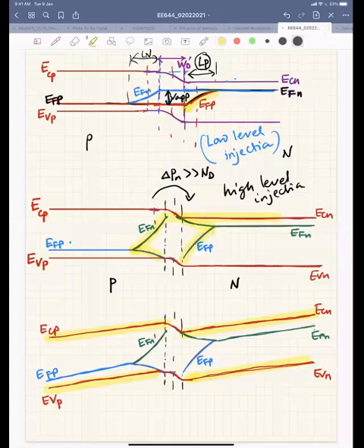See, some diodes come with a current limiting resistor, but then it could withstand a little bit more current or more applied voltage. You could connect a resistor in series with the diode. Basically, you are applying a voltage, then dropping some part of it across that resistor.